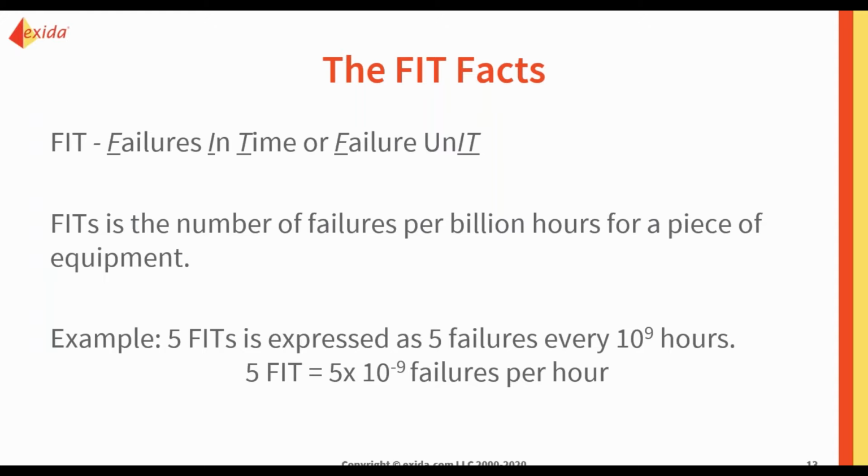So you might hear something like, it is 5 FITs for that screw, or this valve is 500 FITs. That technically means 5 times 10 to the negative 9, or 500 times 10 to the negative 9. And that's how it's described.